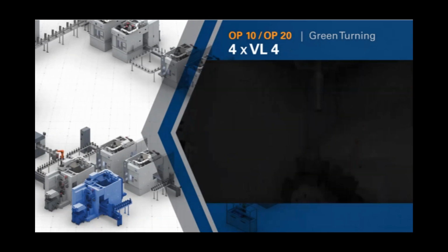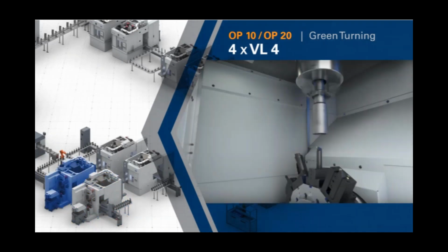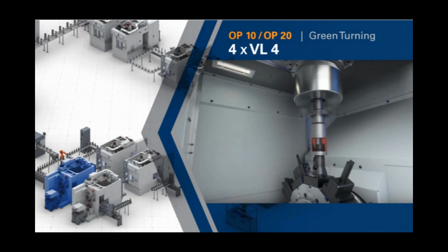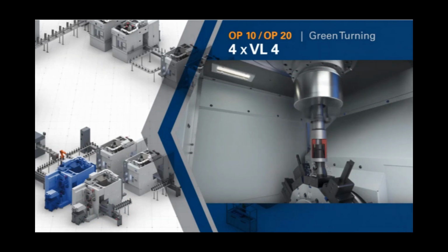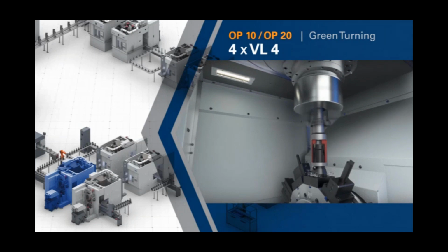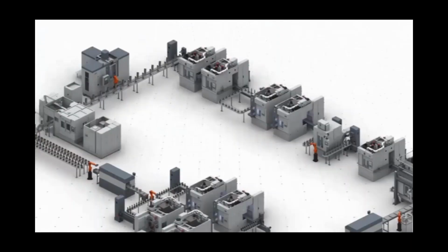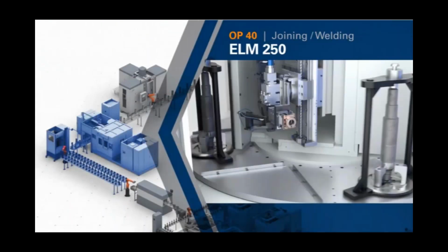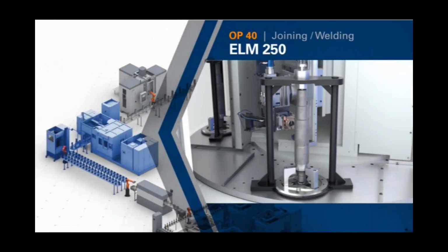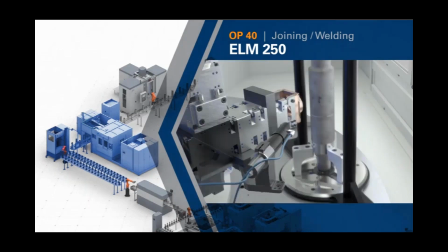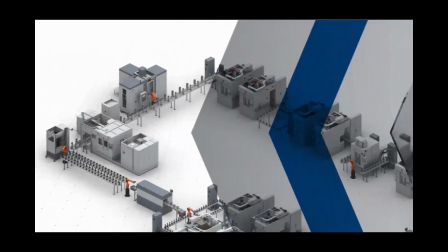So this line that I'm showing you is actually an e-rotor solution as well. It's made from two parts. This is the second part B, doing the op 20 turning. And the reason why some e-rotor shafts are two parts then welded, which is the next operation here, is due to the nature of the need for a lightweight design. So by boring out those two IDs independently, then welding along the seam, you do get a lightweight component.